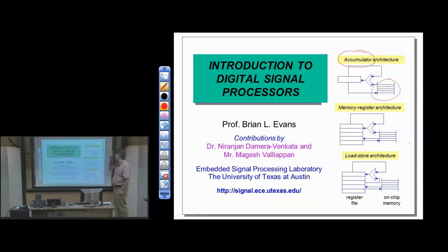So in this particular processor, it was a 16-bit by 16-bit multiplier for TI anyway, and a 40-bit accumulator. So you could accumulate many multiplication operations before you hit the 40-bit word size. So now my question is, how many 32-bit numbers would you add together before you reach this 40-bit worst case resolution or precision? How many would it take? This is a great interview question on campus. If I want to add a bunch of 32-bit numbers together, how many do I add together before I hit the 40-bit long word in this particular processor?